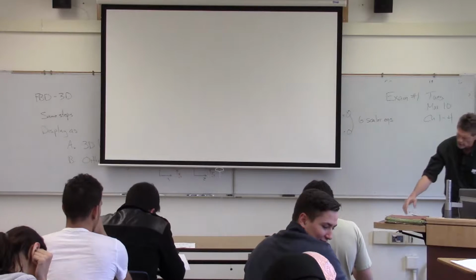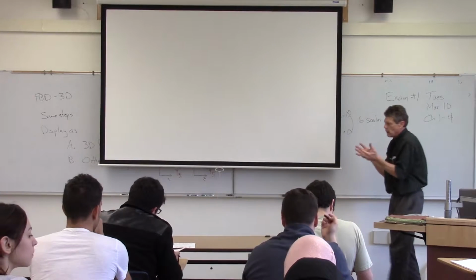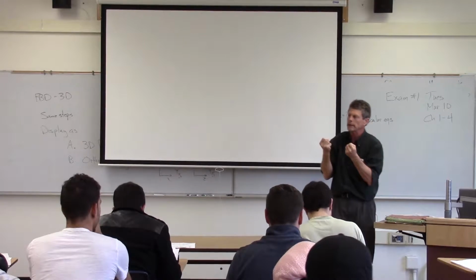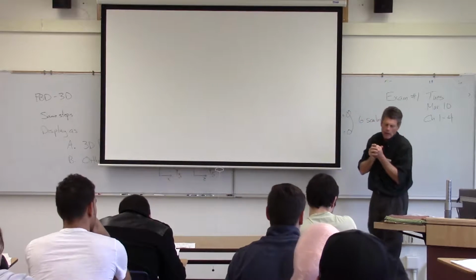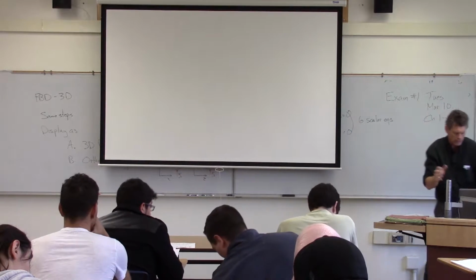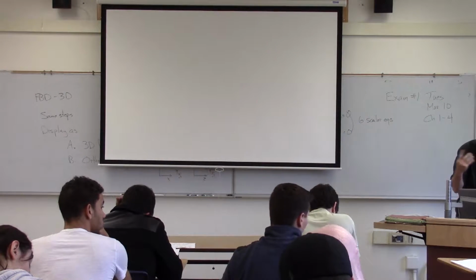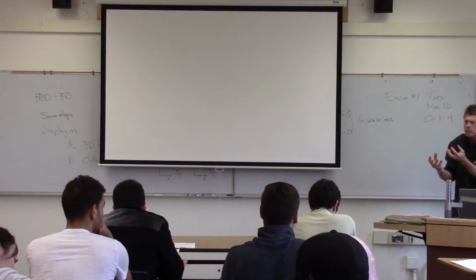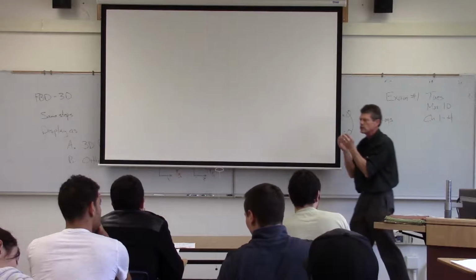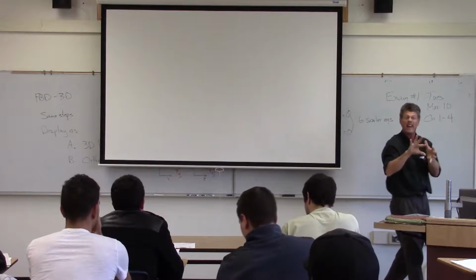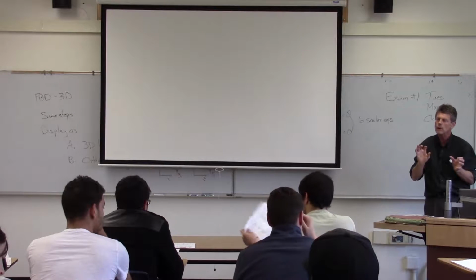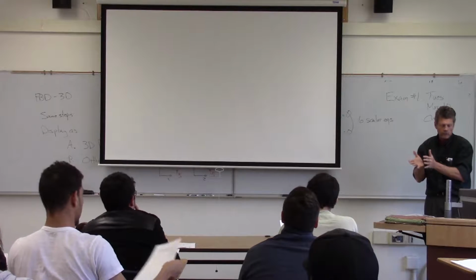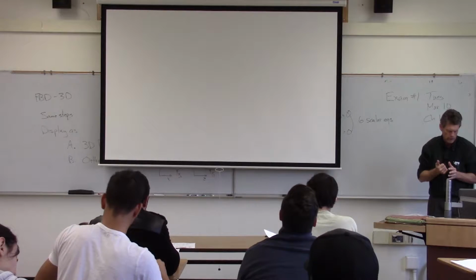What we're going to start off with is, once we talk about creating this free body diagram, we're going to be pulling it away from other bodies, and generally some sort of supports. We need to think about those support forces in terms of how we're taking them out and what's replacing them. So we take the supports, remove them, and replace them with the forces. Think about the translations and/or rotations that are being resisted. If something is saying, I'm not going to be able to go through you, then that support is basically going to be providing a force in that direction.